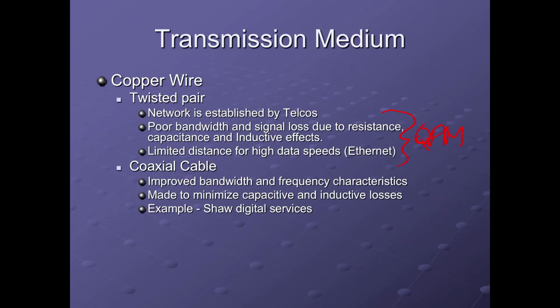So for TELUS, because they can leverage twisted pair, and the fact they have a dedicated line back to the central office, which I'm going to call the CO, they can have a main pipe connection as a data trunk. With a data trunk leaving the CO, they can move huge amounts of data, say over fiber or one of those synchronous data links that we talked about, and each one of their subscribers is a separate twisted pair drop to the central office.